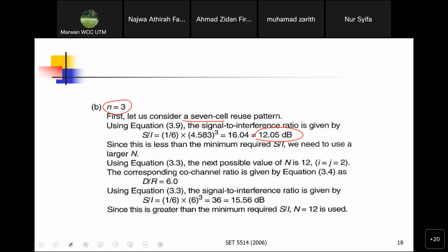So for an interference limited system, it turns out that the path loss exponent plays a very crucial role. Because we know for our cell, there are 6 around. For the interference coming in, if n is bigger, what does it mean? It means that the power of interference is going to be lower.